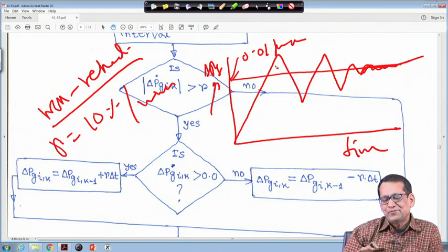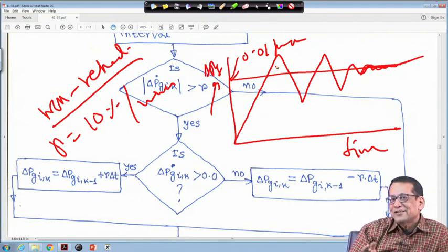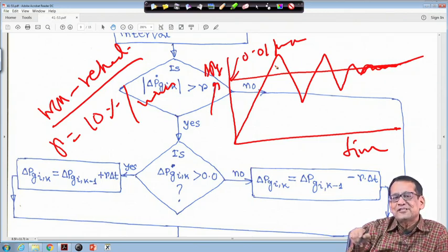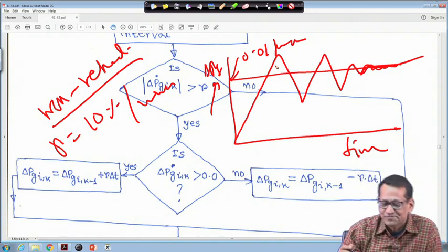But in reality, if you go to the control loop and try to see, frequency cannot be like the ideal case, the way you got for a step load disturbance, because in power systems loads are continuously switched on and off. So if you see the control room, you will find that frequency is continuously changing, but it is not losing synchronism unless some abnormalities happen in the power system. Generation also is not settling; it changes throughout the day, because load is also changing throughout the day, right.